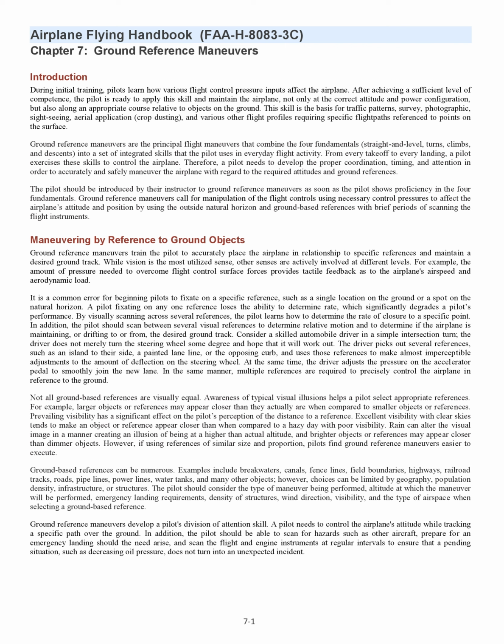Therefore, a pilot needs to develop the proper coordination, timing, and attention in order to accurately and safely maneuver the airplane with regard to the required attitudes and ground references. The pilot should be introduced by their instructor to ground reference maneuvers as soon as the pilot shows proficiency in the four fundamentals. Ground reference maneuvers call for manipulation of the flight controls using necessary control pressures to affect the airplane's attitude and position by using the outside natural horizon and ground-based references with brief periods of scanning the flight instruments.